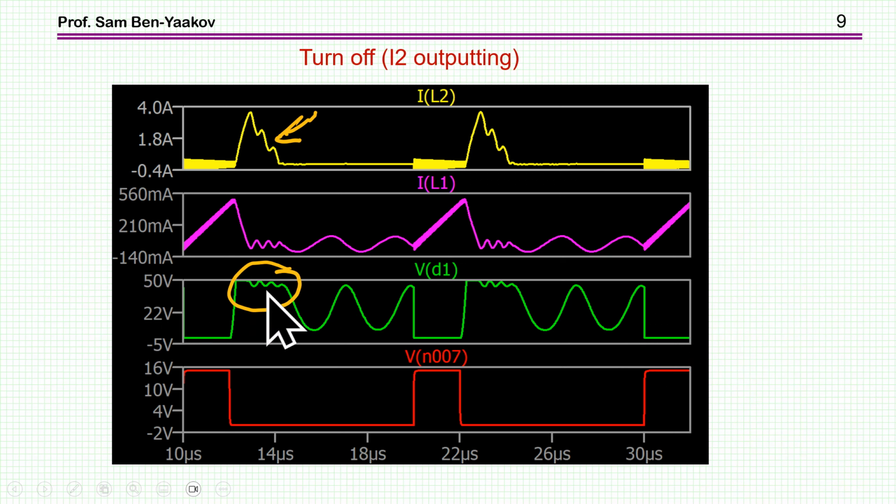We see here the voltage on the transistor, and we see, of course, the current through the primary winding. This is where the leakage is, or where we have reflected it to. And we also see it reflected to the output, which is at that time conducting, because we are just after the turn off, and there is a current at the secondary.